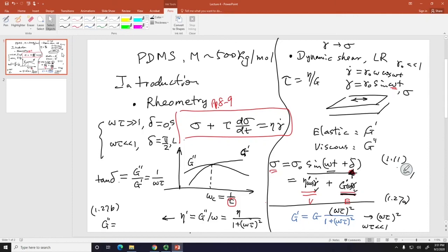Okay, so you're jumping a little bit one step ahead. DMA is a device, and I was about to talk about rheometry. DMA typically is a device where you do stretching, like this. And obviously, I cannot hold a piece of water that way. So for your material that is water-like, you have to use this mode, shear, to learn the same information.